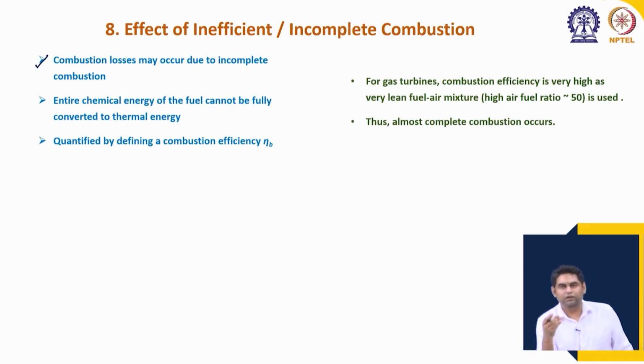Incomplete combustion may occur if there are local regions where the oxygen concentration is lower. This can also happen if the flow is too fast and the time that is needed for complete reaction is not available for the reaction to occur. Okay. If the flow is too fast, the combustion products will blow out before the complete combustion occurs. So, it can also happen in those cases.